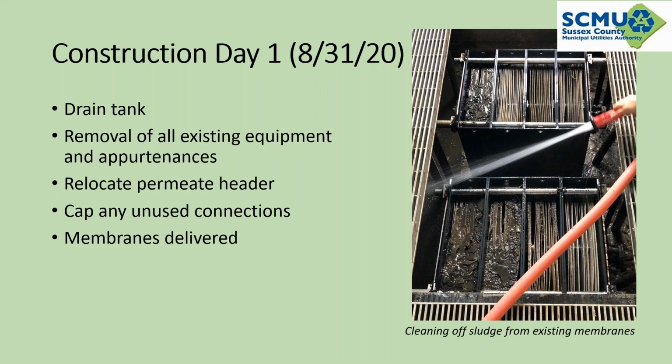So really, that first day, the MUA drained everything. We cleaned out the chamber, and then the manufacturer proceeded to remove the units. They began relocation of the permeate header. They capped any future unused connections, and the new membranes were delivered to the site.